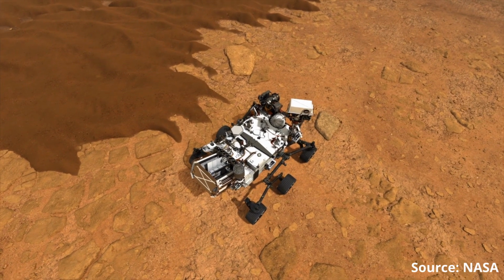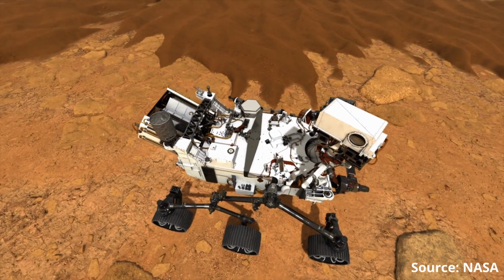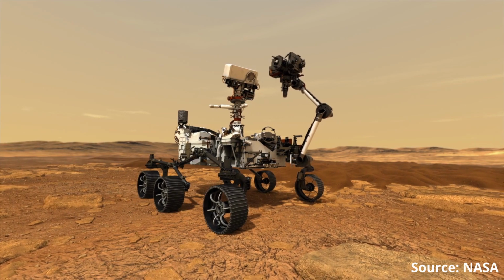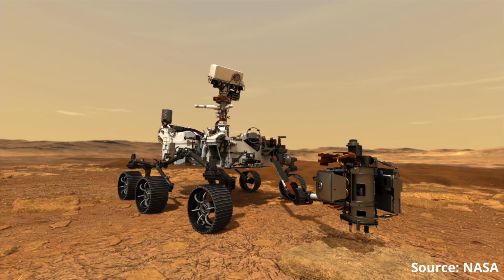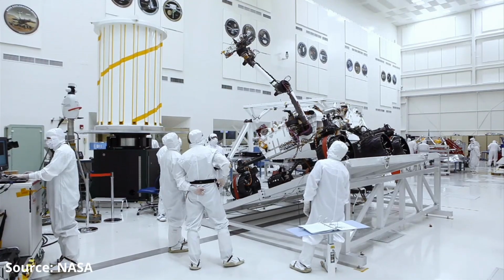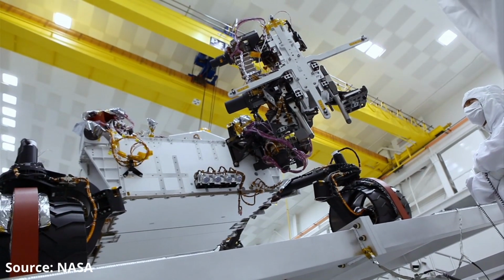The end effector of a robotic arm in a rover sense can be any tool like a scoop or a grinder, or a scientific instrument like a spectrometer. When using a robotic manipulator on a rover, we face some limits and challenges. First of all, there are certain mass and volume constraints which we have to adhere to by design. Typical rover-mounted systems are generally of low mass at around 1 to 3 kilograms and have to be stored in a compact way to not interfere with rover operations. Therefore, most rovers actually give up 1 degree of freedom by not including a roll degree for the robotic arm. In many cases, this is not needed anyway, so the trade-off might be worth it.